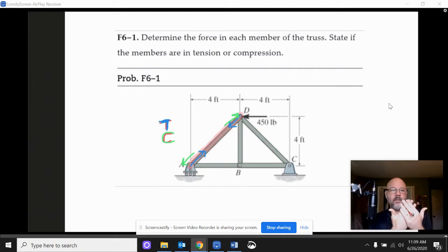Imagine a rivet going in there. Now, the pin cannot pass any moment, so you need to think of all these joints as being floppy. They could all flop around, and so we have to have all this structure around them so they don't flop apart and they maintain the shape that we want them to have.